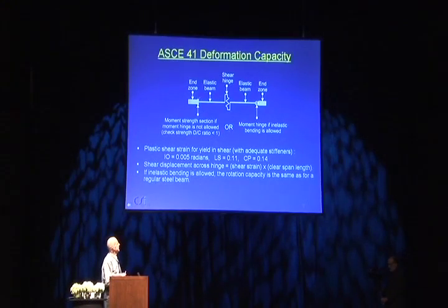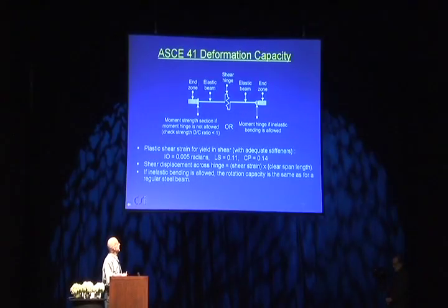Or working backwards, if you intend that the shear link yield only in shear and does not yield in bending, what you might do is put in a moment strength section, then calculate the strength on that just to make sure that the strength demand capacity ratio is less than 1, which means a moment hinge does not form. And if the demand capacity ratio is larger than 1, then a plastic hinge does form. This is not what you intend. You need to redesign your shear link.